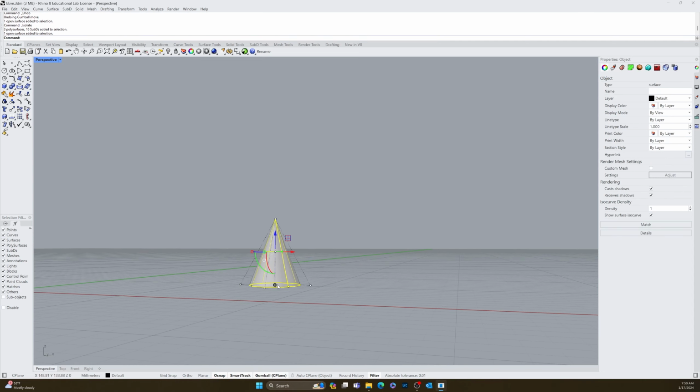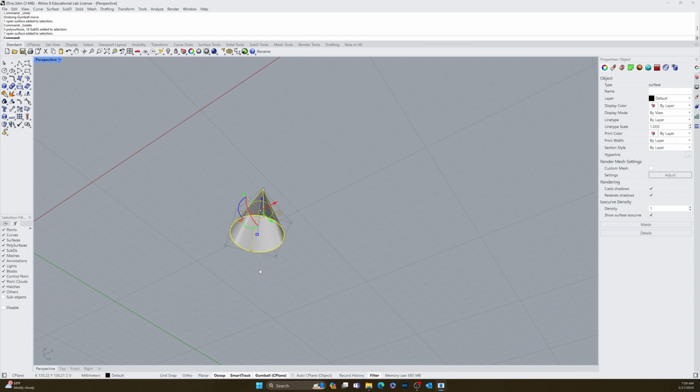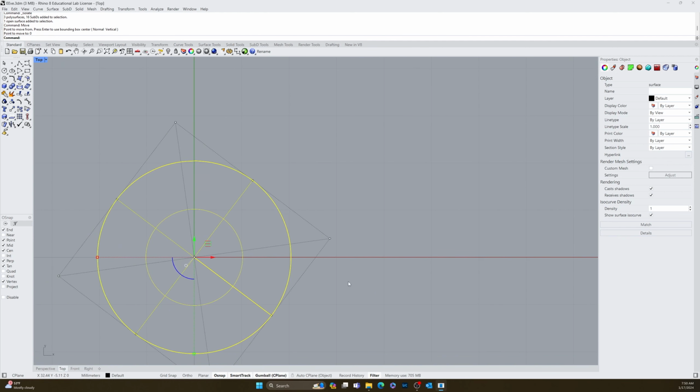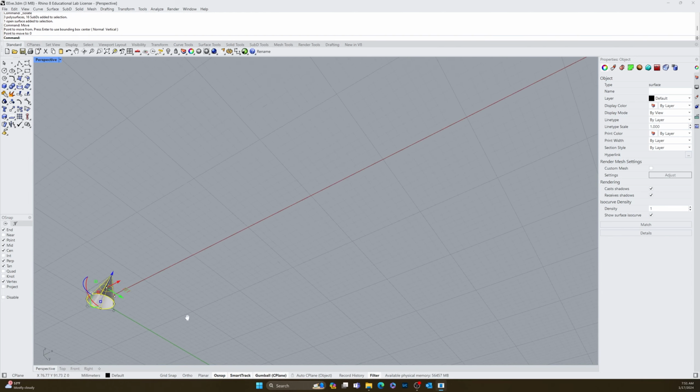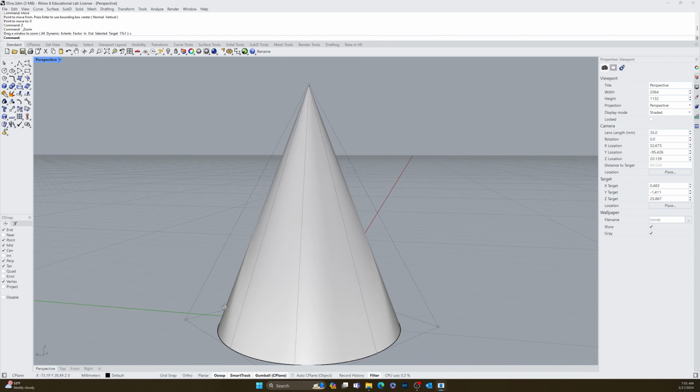Okay. And as always, I like to work on this at the 0 level. So I'm going to move, enter, with our snaps, with the center snap on. I'm going to highlight right there and click and go 0, enter. So that when I switch to a front view, we're in the middle. When I switch to a top view, we are also in the middle. So front, perfect. Perspective, back here. Z, enter, S, enter to zoom in on the selected object.